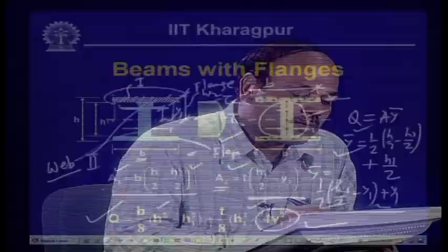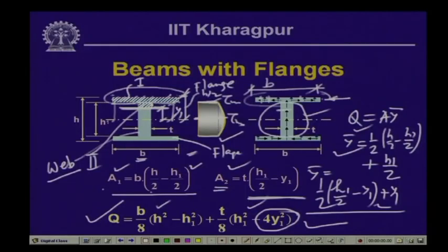Now, at this particular section you can appreciate that the shearing stress is 0 on the surface of the section. So, if you look at the bottom part of this beam at this section, here the shearing stress is 0 and at this particular section shearing stress is minimum. Hence, at this cross section there is a complex distribution of the shearing stress, and as a result we cannot apply the shear formula for evaluating the shearing stress in the flange zone. So, this is how we compute.